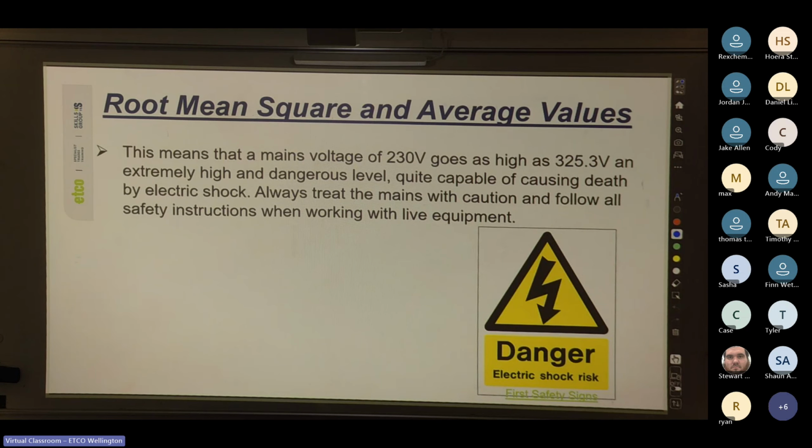So basically you're going to hospital to get an ECG. You're going to be there for between 2 to 4 hours, and they're going to check that your heart's going in the right rhythm. On the elite course that I was teaching in Auckland, they were asking, how bad of a shock does it have to be for you to go to hospital? Simple answer is, if you feel it, go. Doesn't matter. The smallest little thing can throw your heart out of whack. So if you feel it, you're going.